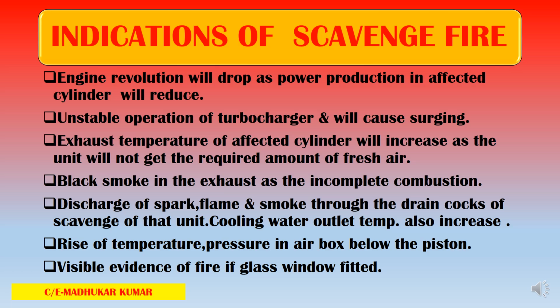Now we are going to see the indications of a scavenge fire. What are the various indications? How can the scavenge fire be identified? So first, engine revolution will drop and power production in the affected cylinder will reduce. The cylinder having a scavenge fire will produce less power, and finally the engine revolution will also drop. Unstable operation of the turbocharger will cause surging.